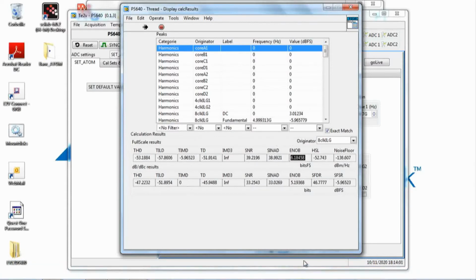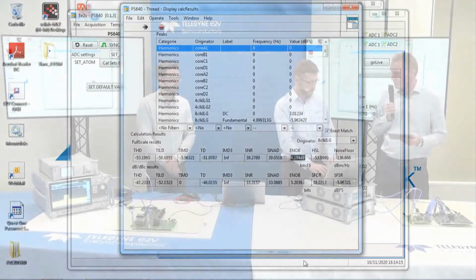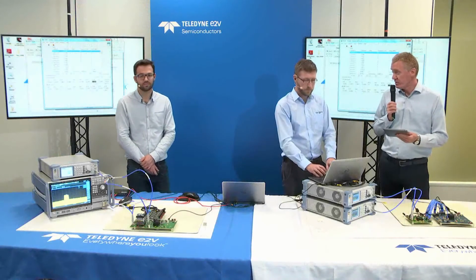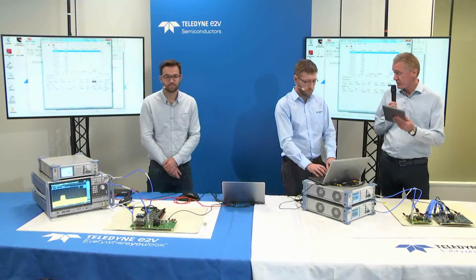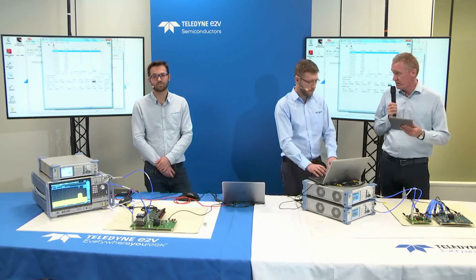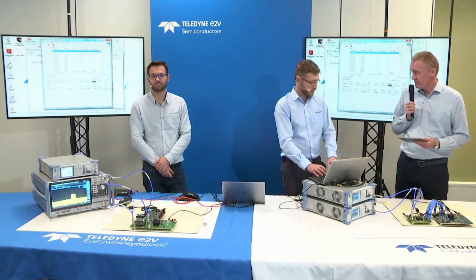I have to check on the generator. So here it's a bit higher than 0 dBm in order to have the -6 dBFS at the output of the A to D converter. Right. So maybe it's worth when we pause a second on this. You see a live performance measurement, 6.2, 6.3 bits of ENOB with a single tone sine wave at 28 gigahertz, and the power coming into the ADC in single-ended is just slightly above 0 dBm.